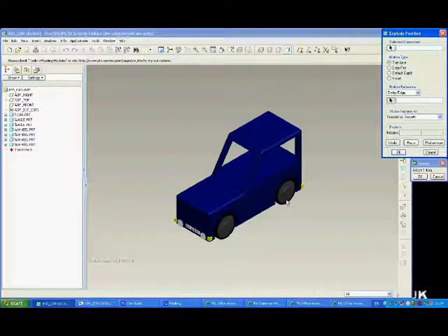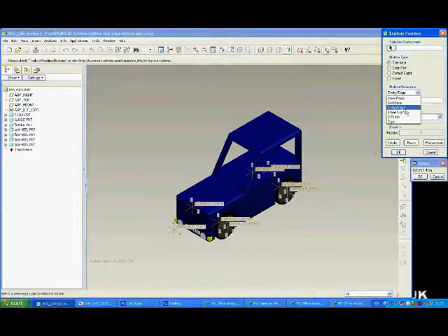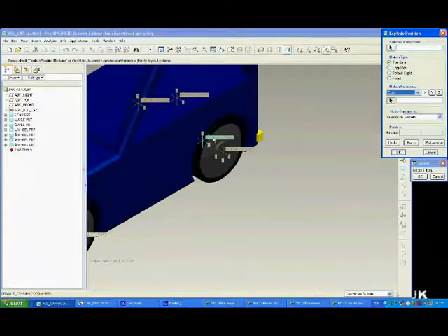I want to make sure this wheel moves in this direction here, so I want to turn on the coordinate systems display here. Now, I want to leave the translate option selected here, and I want to select the coordinate systems here. If I zoom in, I can see that for the wheel, the coordinate systems display is this one here, and the X direction is in this way. That's the way I want, so I want to make sure the X direction is selected here.